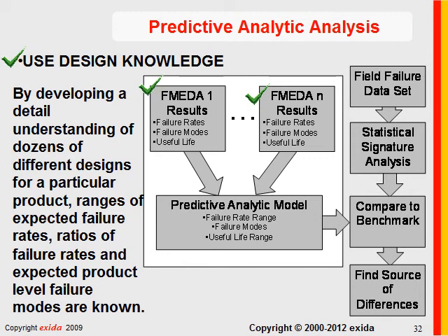Another question, does Exida data tend to be more conservative than end-user field data? The answer to that is yes and no. That's a good question. Thank you. Exida FMEDA data is calibrated to be more conservative than real field failure rates attributable to a product. Now, what in the world is that weasel word? If you don't know that phrase in the United States, it's a term where you're trying to avoid explaining something, but I am not. What I mean is all